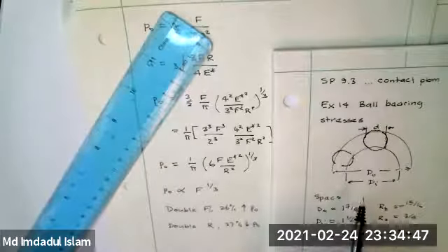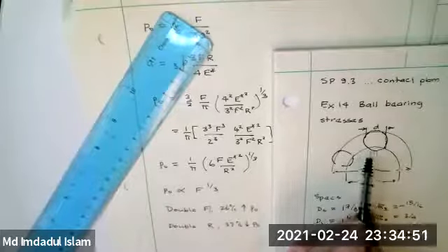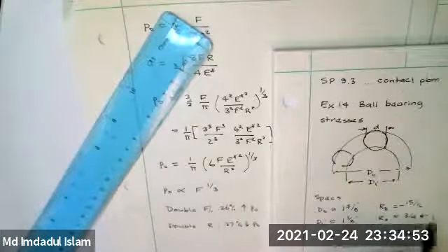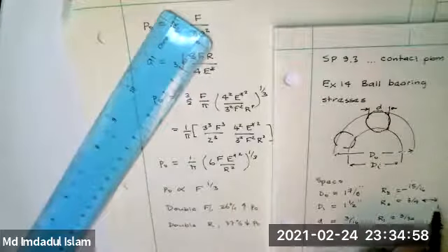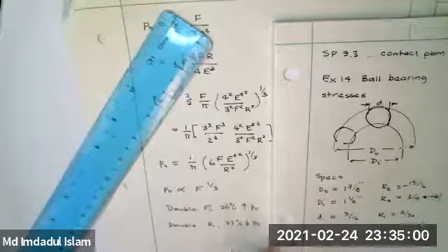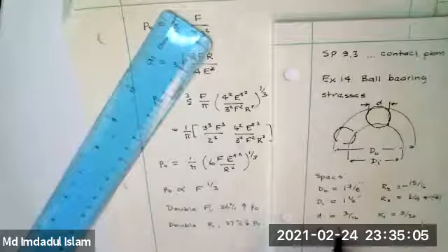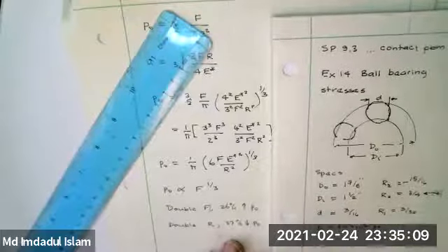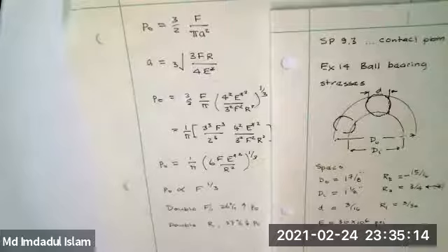So the key stresses are going to occur at the inner radii, the biggest stresses. This is what we're going to concentrate on. This is steel. 30 times 10⁶ PSI is a common value taken for steel. Steel varies a little bit, probably between 28 and 30. This is a standard sort of value.